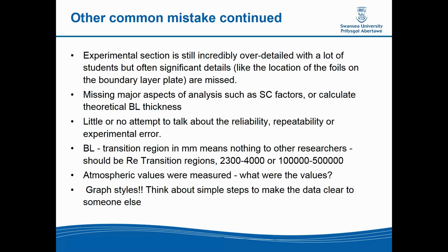Some of you have taken that from the user manual. That's absolutely fine, with appropriate reference. But that detail does need to be there. And that detail also is the same for the stress concentration experiment. So often you've said, here's a picture of my test bars, and you haven't put what is the size of the hole, what is the size of the gauge length, the thickness, a lot of the details that would mean that somebody who was going to try to model that or replicate your experiment wouldn't be able to do it because they wouldn't know what the length of that test bar was. So those are very much the essential details of what you need in the experiment.